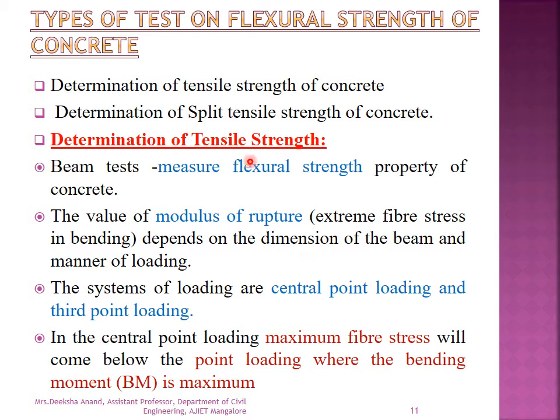If we go for a beam test, we all know how beams are cast. A beam is nothing but a reinforced structure, where we have reinforcement and inside that we cover it with the concrete. It is a measure of the flexural strength property of the concrete. The value of the modulus of rupture, that is the extreme fiber stress in bending, depends on the dimension of the beam and the manner of loading.